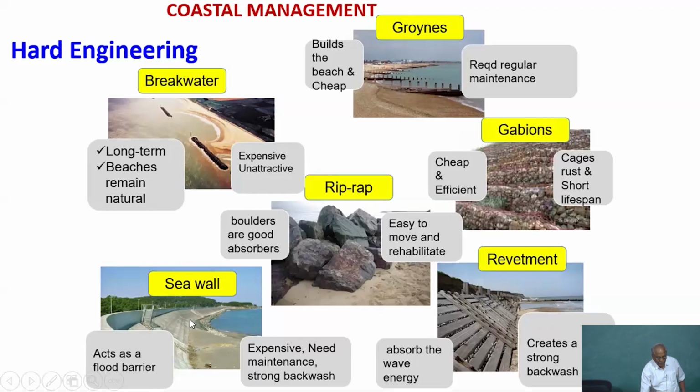Then seawalls. This is a concrete seawall, which is going to be very expensive. So people resort to the rubble mound seawall, with a stone weight of maybe about 1 to 2 tons, maybe slightly more also, with a slope of about 1:2 or 1:2.5, depending on the importance of the stretch. And then you have to design it, and the crest elevation of the seawall is also extremely important. When you address climate change, you have to take care of the crest elevation.